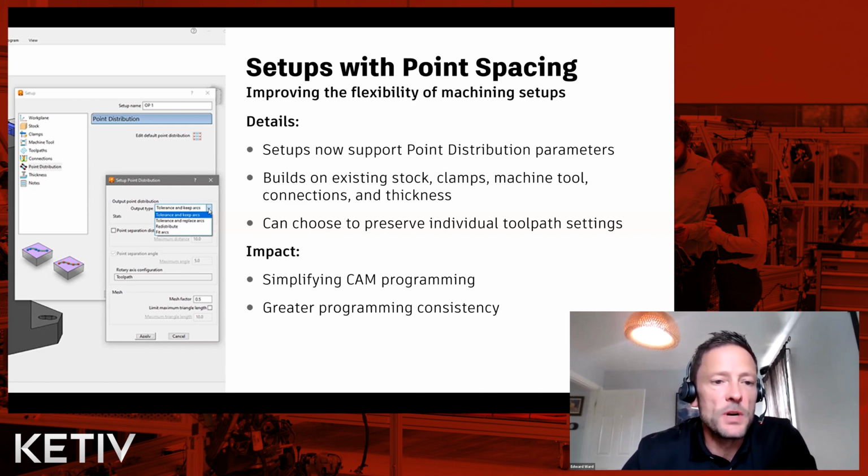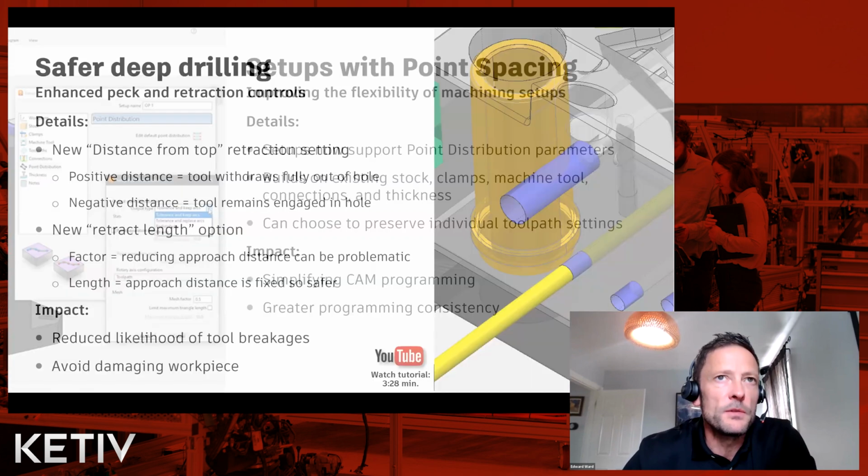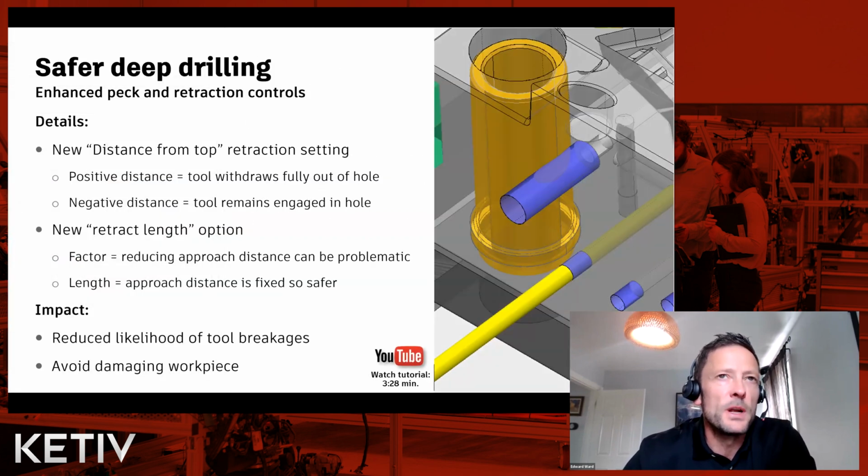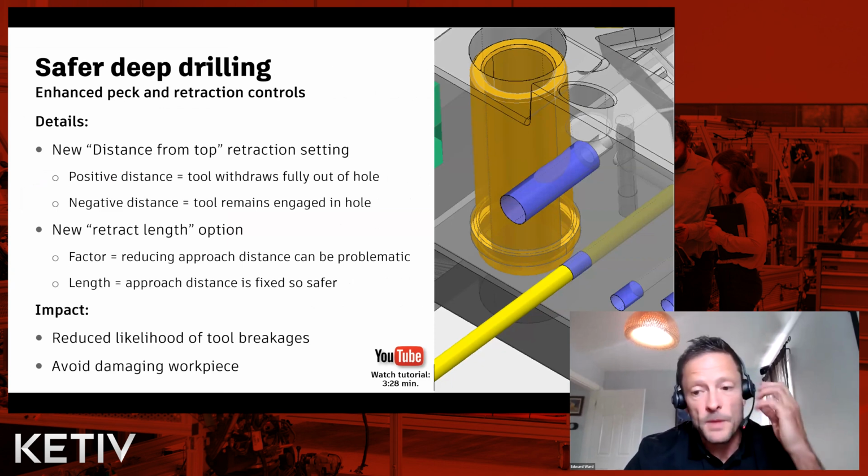Safer deep drilling, yeah. So with the traditional, let's call it a deep hole pecking cycle, depending on the depth of the hole, there was a bit of a safety issue with previous methods, and you didn't have this functionality where you could control whether you wanted the tool on its pecking cycle to come out of the hole fully or even stay in the hole.